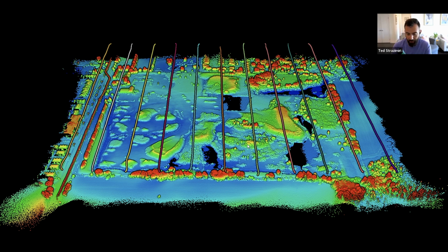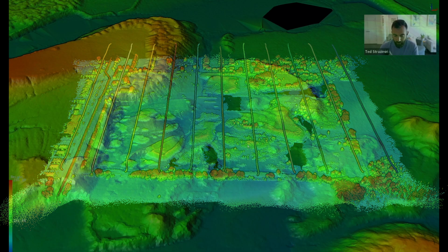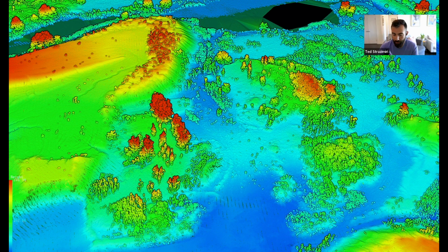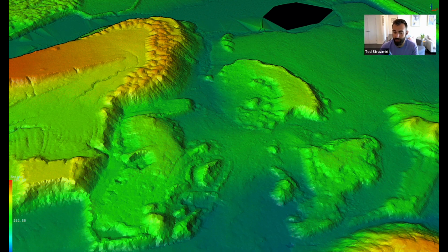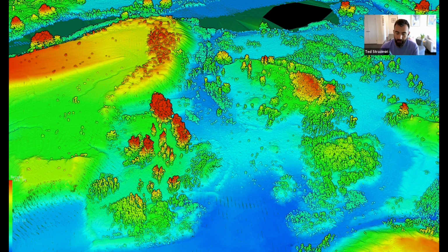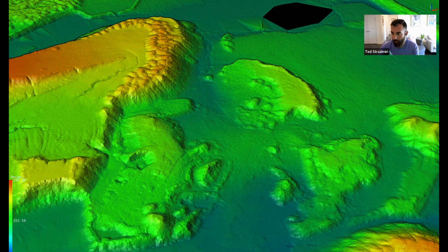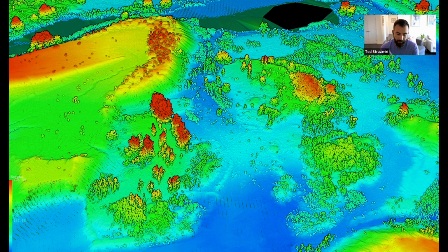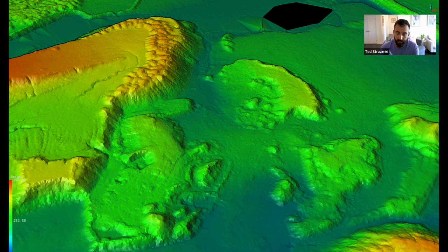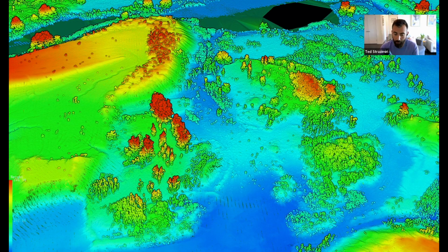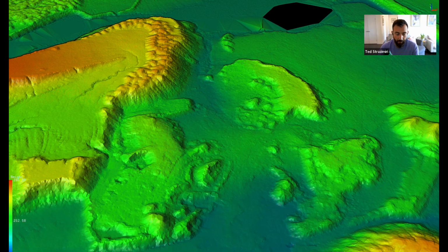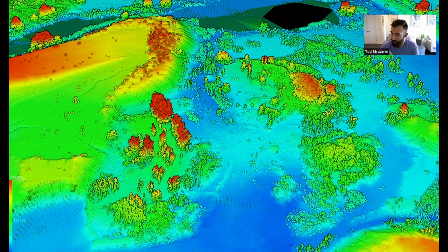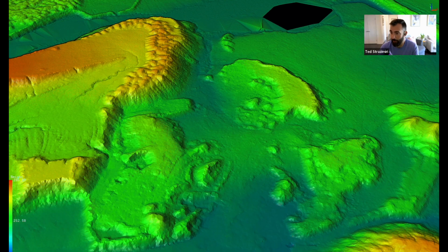So this large site, if this was done manually, they told me this would have been about 2 weeks of work. And so their task was to measure all of the volumes in these piles. The real sort of wow moment happens when you see the amount of vegetation that was on these piles. And then thanks to that classification, right? Just classify ground, get rid of everything that's not ground, and that leaves you with the bare terrain, bare earth model. And from that bare earth model, we can again measure those volumes very, very quickly.